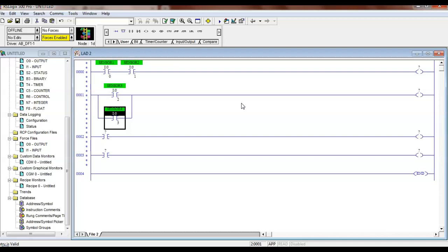And what's nice is that we're transposing or taking programs that were written for Allen Bradley, and they've got all the symbols in there for you. So once you set up your symbol chart, you can look at the Allen Bradley program and draw the circuit and just type in. We're gonna set up a symbols table first to just determine what input on the Siemens corresponds to the input on the Allen Bradley, because they address it differently. Or you can do it this way.